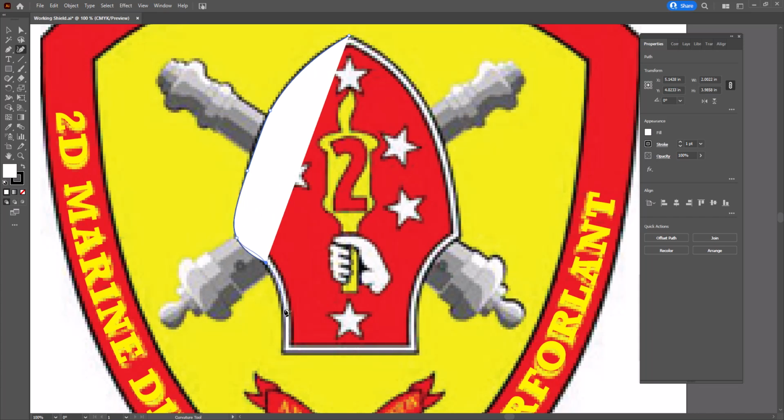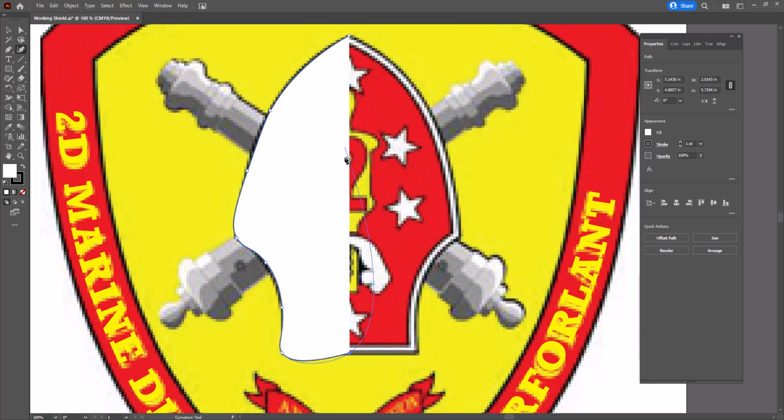And like we did before, we'll come back and fix these corner points. And I'm just going to come down here. I'm going to hold my shift key down, and this is going to lock in that horizontal location. And I'm just going to pick right here where I think is about the center, but we'll fix that afterwards. I'm going to come up to this tool here and we will start changing the anchors of our corners. So we can make these sharp corners.